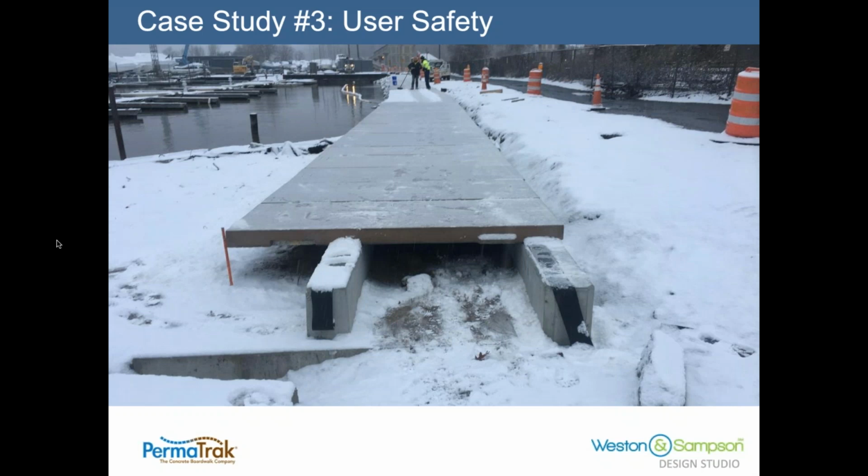It may look odd to you that the deck planks, or what we call the treads, are hanging over the edge on the left-hand side. Those are purposely being done that way. They were structurally designed that way. The designer wanted the users to not only have enough travel space, but they wanted to be able to stand and look over the water. And then in the summer months, to be able to turn their heads and look at the fireworks and listen to music that was taking place in the park.